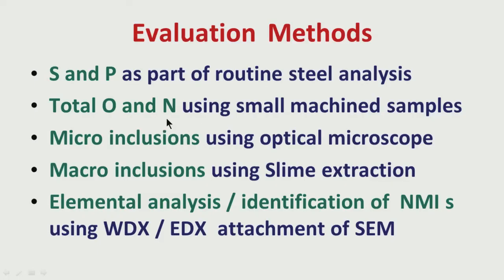In this regard, there is no change in nitrogen. When the sample is getting heated up, we increase the total oxygen in steel because of oxidation, but there is no nitrogenation of the steel. So, nitrogen remains the same. So, from nitrogen analysis also we can understand before and after. If you machine it too much and the sample gets heated up, we will find that the oxygen reading is going up, but the nitrogen reading does not increase. That gives an indication that there has been some increase in oxygen during machining. So, we have to be careful about that, so that we do not get an erroneous result.